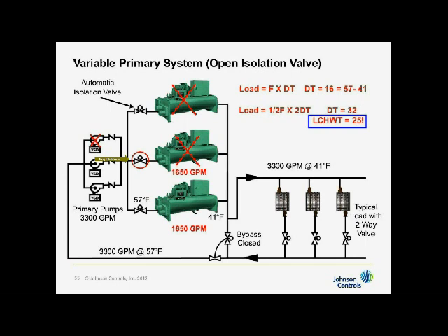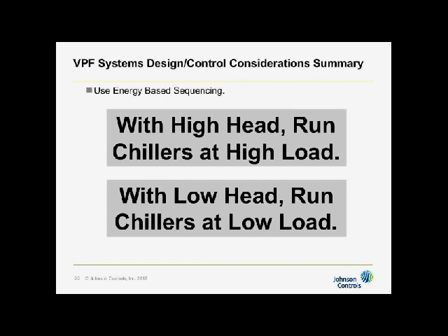This is why I said earlier we need modulating valves to open up over the course of 1.5 to 2 minutes. Okay? That way it solves that problem. This opens as fast as the vanes close and the problem goes away. Okay?